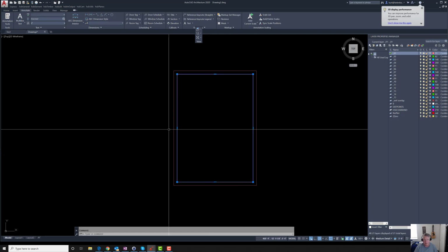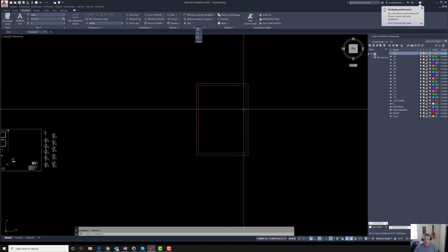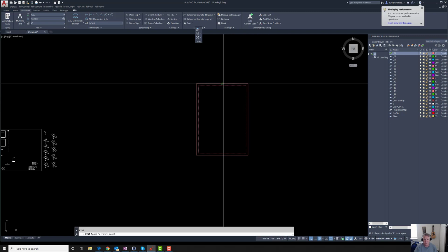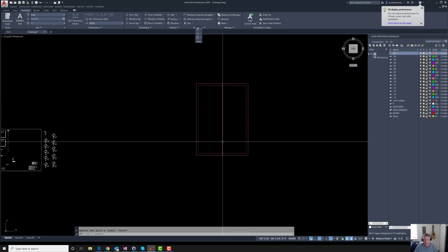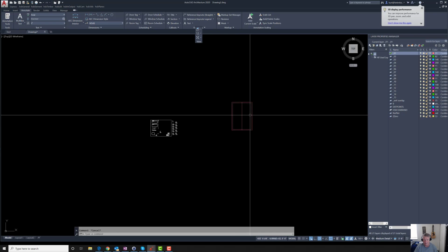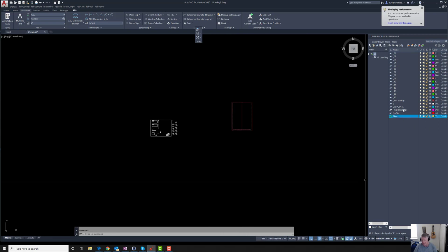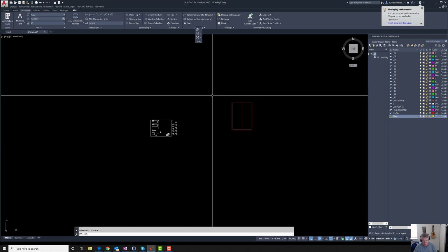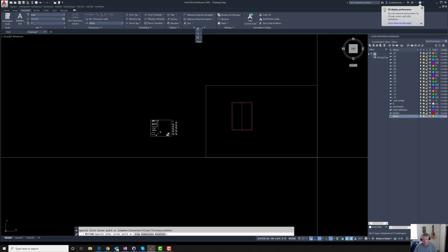And now in CAD, it can be helpful to change these things around a little bit so that you can keep track of what you're looking at. I've made that dashed now. So this is our roof, and we're certainly going to have a ridge running down through the center of it. It's going to get truncated off where these hips come up in, but we're going to figure out where that is and draw that accurately. So the first thing I do is draw another rectangle on another layer here, and this represents the ground plane.